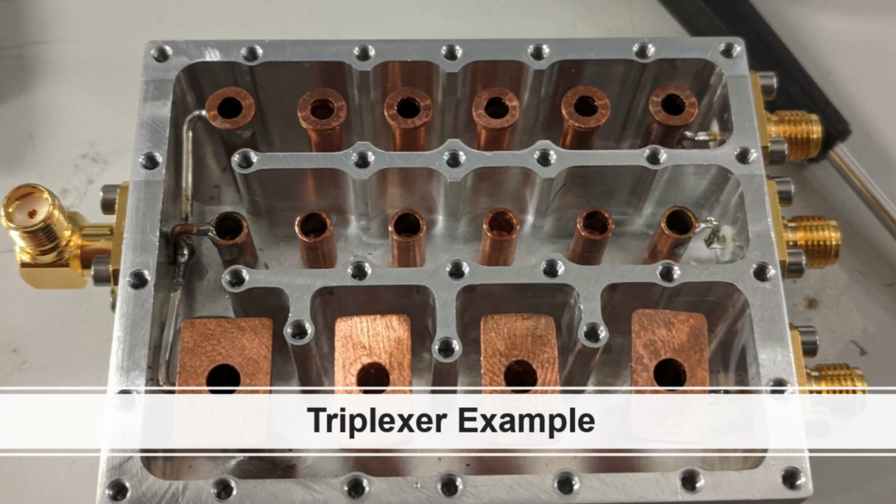Now here's an example of a triplexer. A triplexer is just 3 different bandpass filters in the same housing. They're tied together on the left side here to a common port. That would be typically an antenna port. And on the right, you have low, mid, and high band connectors that will allow you to multiplex different frequency bands onto the same antenna, assuming the antenna bandwidth is wide enough to handle that.